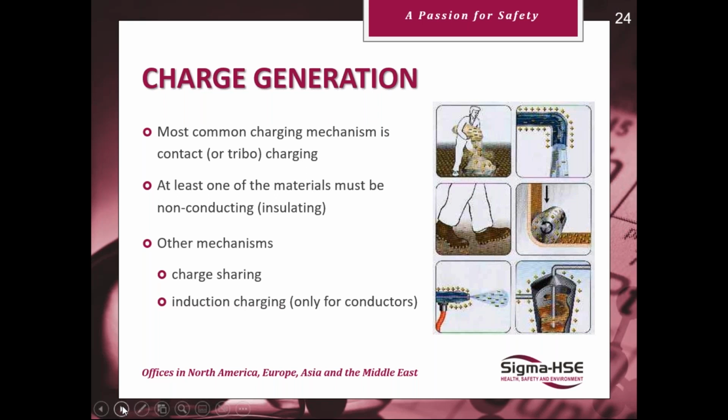Insulating shoes, walking on an insulating surface. Rollers with, say, acetate sheet going around them. Spraying, a very high intense area. And then you've got inside some form of cyclone or something like that. Again, you see charge separation, positive on the equipment, negative on the powder.